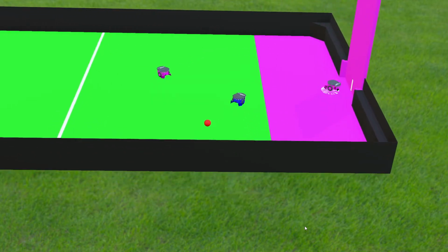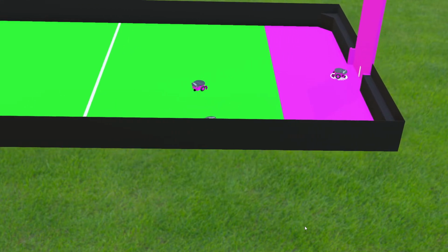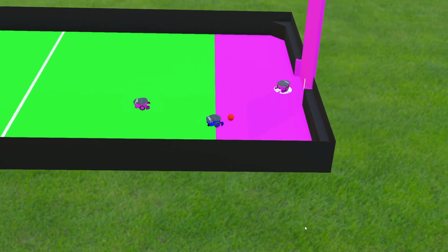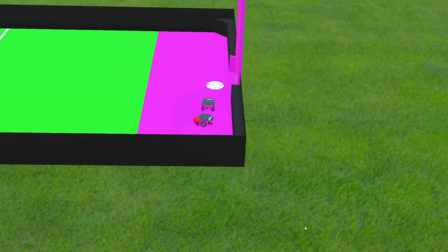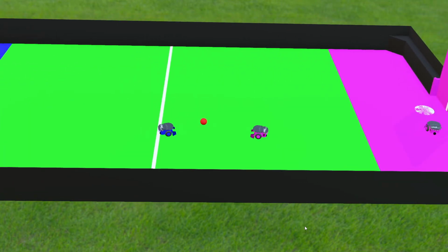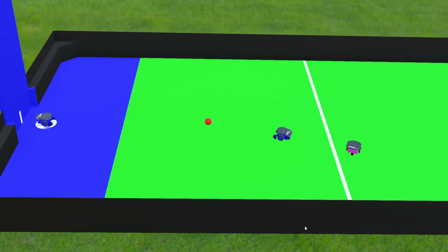Anyway, back to the defender. Once it aligns itself side to side, it will turn to face the opposite direction towards the enemy goal, and then it will either reverse or go forward a set distance, and then it'll be on its white dot. That white dot there, when it's in its watching state looking for the ball, if it doesn't see white there, then it will trigger those states where it'll return back to its white dot.